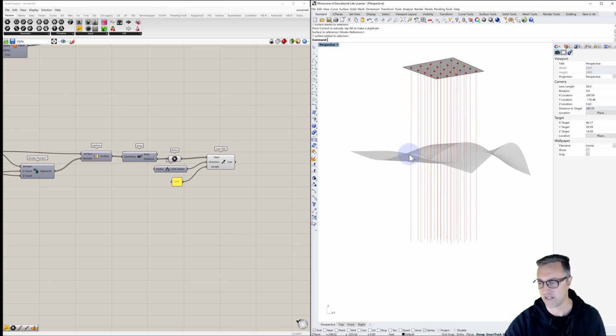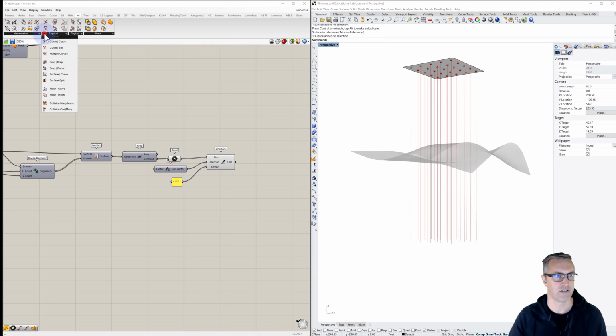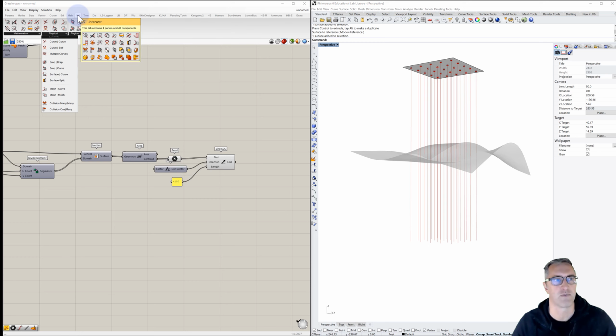The next thing that we'll do is find the intersection between them. So we'll go intersection, mathematical. We're looking for B-rep and curve. And so it's under the physical. So under some of these I remember by heart and I can type them in. Other times I can't. So we're looking for the intersection of B-rep and curve.